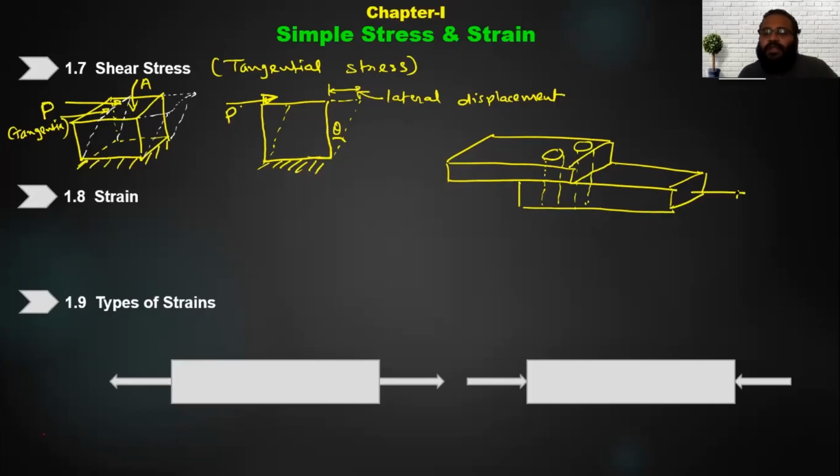Now if you are pulling this plate on one side and pulling the other plate on the other side, what will happen to the nut and bolt you have attached here, these two screws? Shearing action will happen. For example, if I draw that bolt, its cross section and the lower cross section, the load on one is like this and the load on the other is like this.